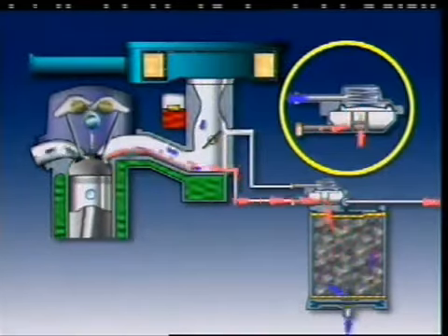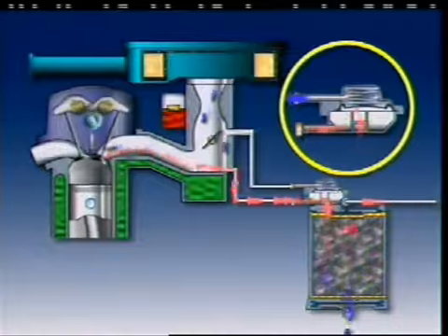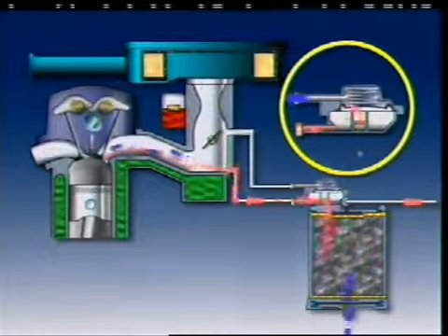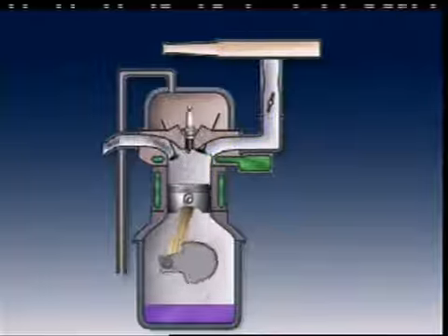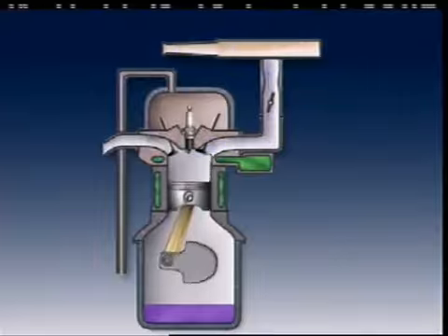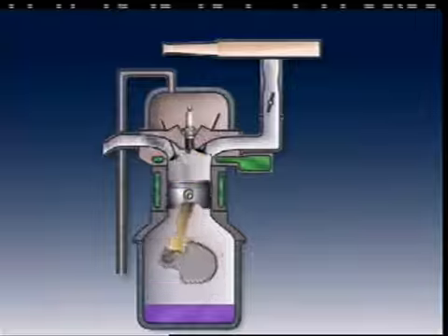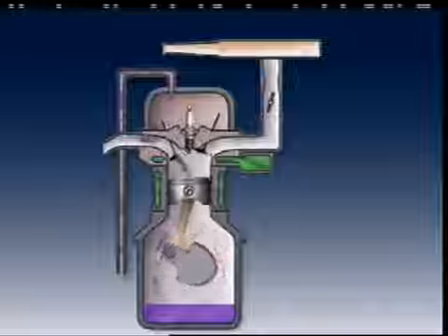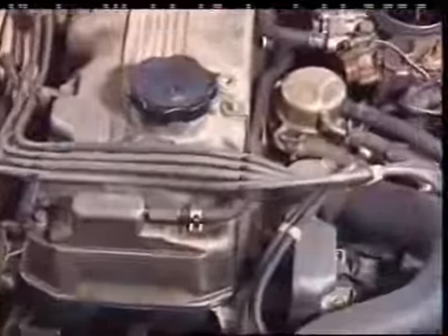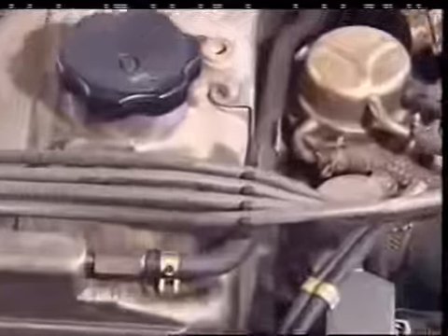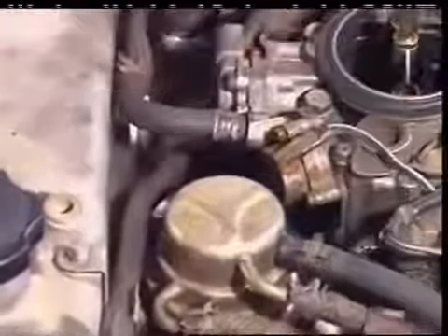of the combustion process. In a petrol engine vehicle, during an engine cycle, some of the gases escape past the piston rings into the crankcase. This is called blow-by. Some of these blow-by gases mix with heated vaporized oil and can usually escape out into the atmosphere. Modern vehicles direct these gases and vapors back through the inlet system to be burned during normal combustion.